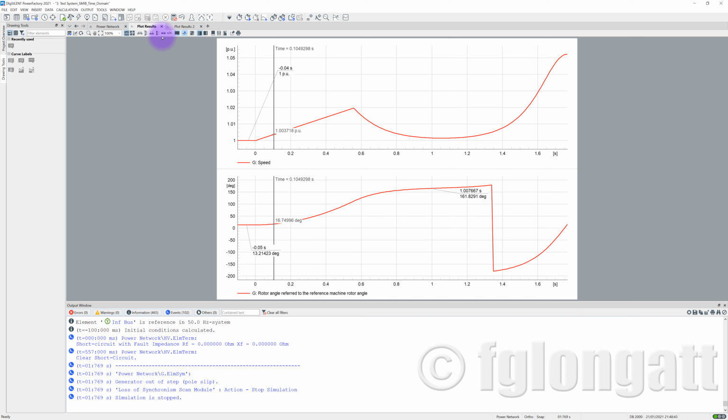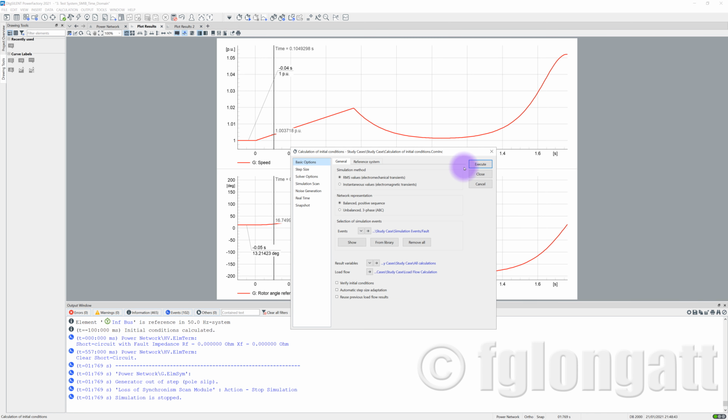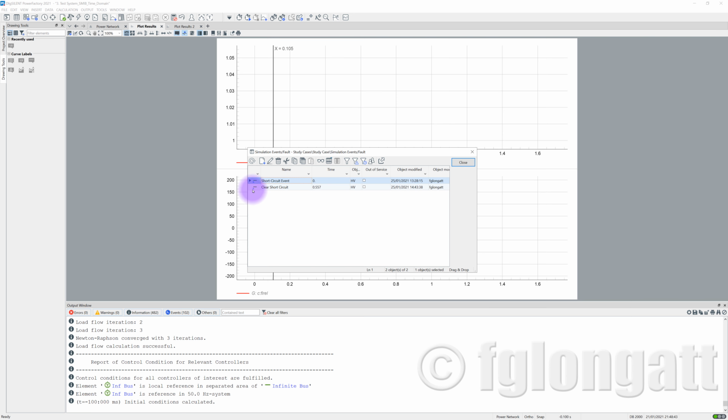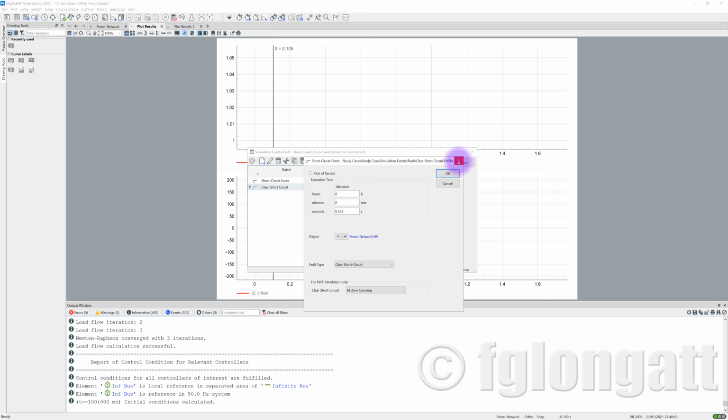And for this very basic system that I showed you, the critical clearing time was 556 milliseconds, okay? Well, I highly suggest to do the following, okay? Here, right now, you have a tool to play games. To be honest, here you have the tool to learn many things. Of course, you need to have time to do that, okay? But if you run initial conditions, at home, when you have nothing to do, I highly suggest to insert here in the short circuit a resistor. If you include a fault resistance in the short circuit, you will realize that it has a very interesting impact on the critical clearing time, okay? I highly suggest that you do that as an exercise, okay?